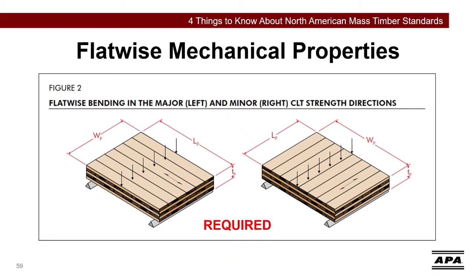For basic CLT layups and grades, this testing is done to confirm the design values shown in Table A2 of Annex A. For unbalanced CLT layups, the current standard now requires a qualification test to be conducted on both positive and negative flatwise bending moment capacity.